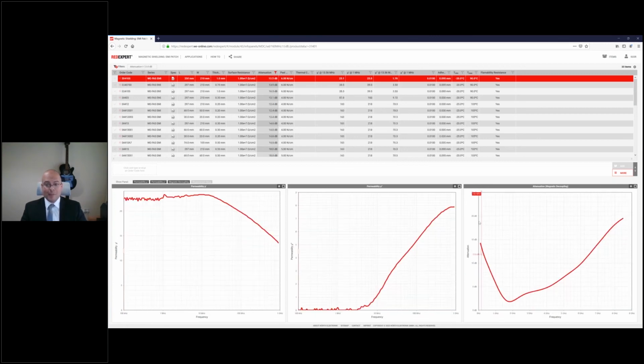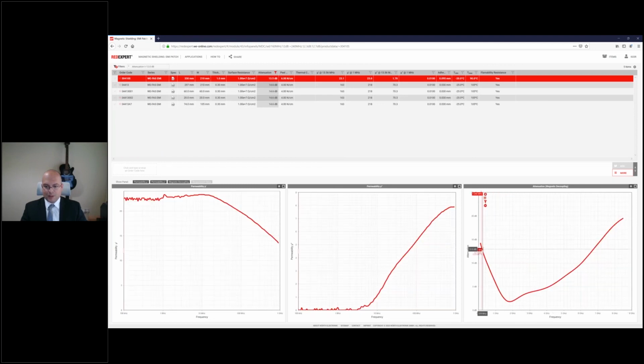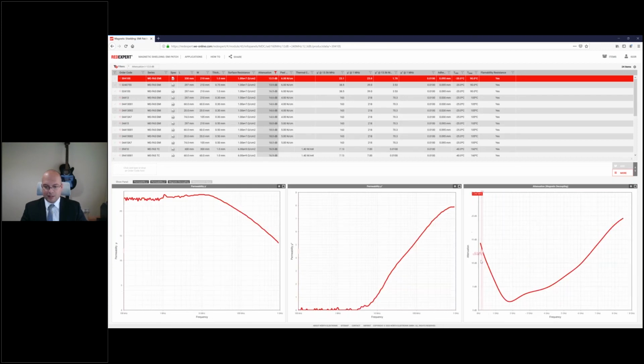Now I'm going to add another marker at 240 megahertz, which is our second frequency, by clicking the plus button here. So there we go. There is a second marker. Let me drag this marker here, and let's put it on 240 megahertz. And now let's finally add another filter on this marker. Click here on filter, and once again, the top triangle, I'm going to drag it to the top, and the bottom triangle, I'm going to click on it, and I'll set here at least 12 dB.